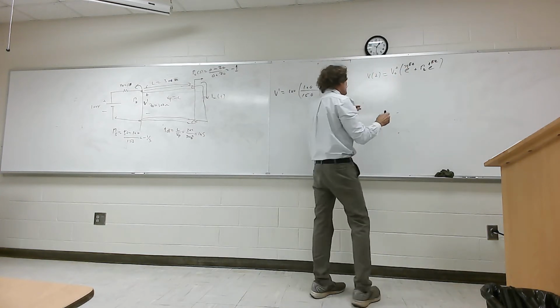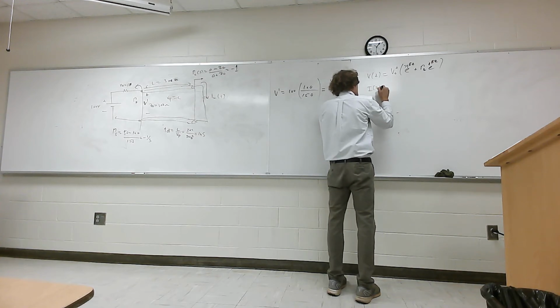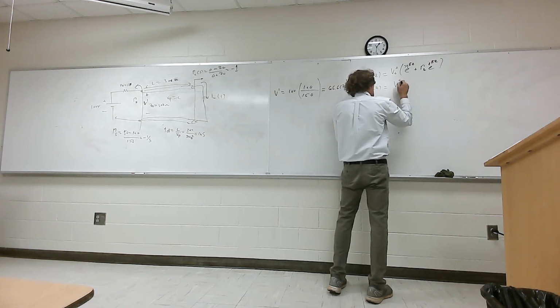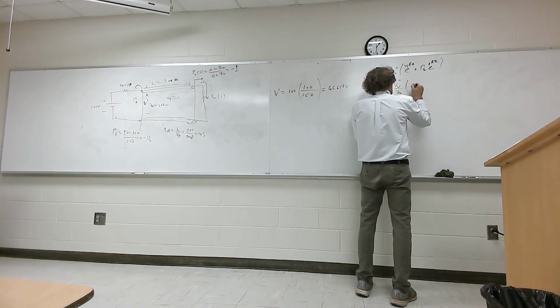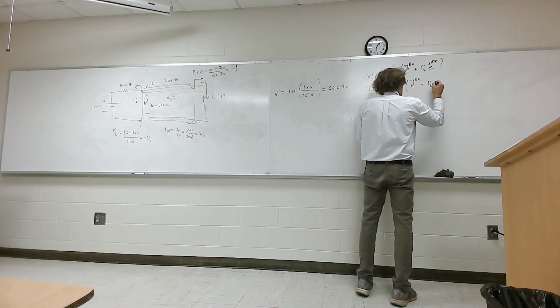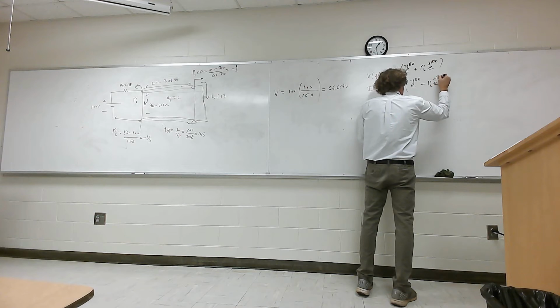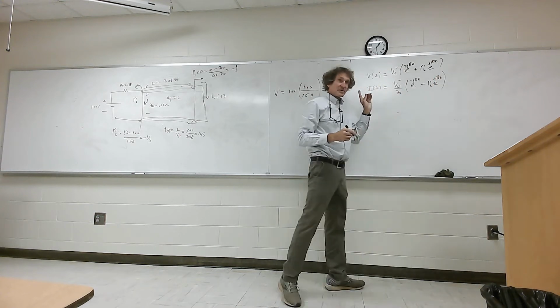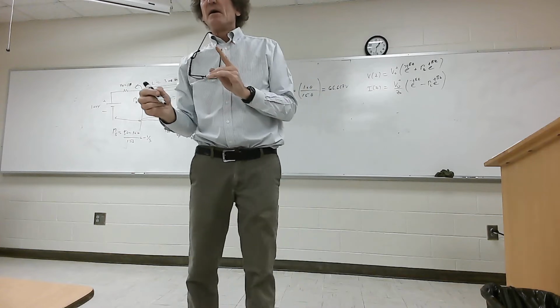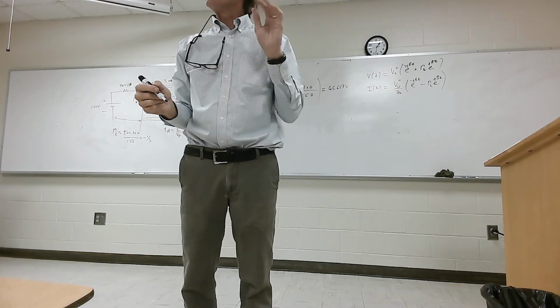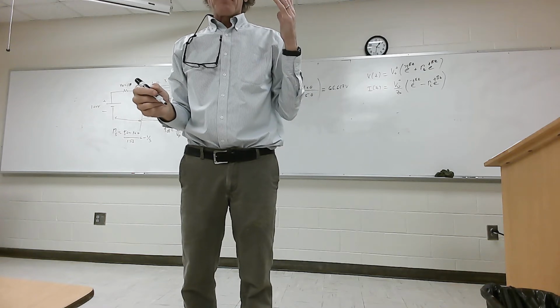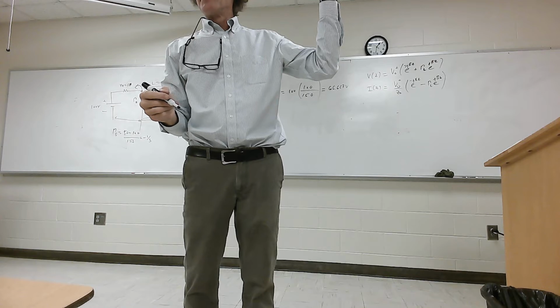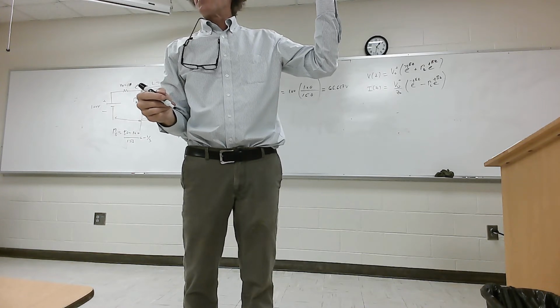So the current, what happens? The current on the transmission line will be V naught plus over Z naught, right? But then it's going to be e to the minus j beta z minus the reflection coefficient at the load times e to the j beta z, right there. You all follow me? That's a minus reflection coefficient. Take a look in your book if you don't believe me. It's a negative sign, and the reason is the waveform is traveling in the opposite direction. And you'll get that. Now, how many remembered that, by the way? Kind of, sort of? All right.